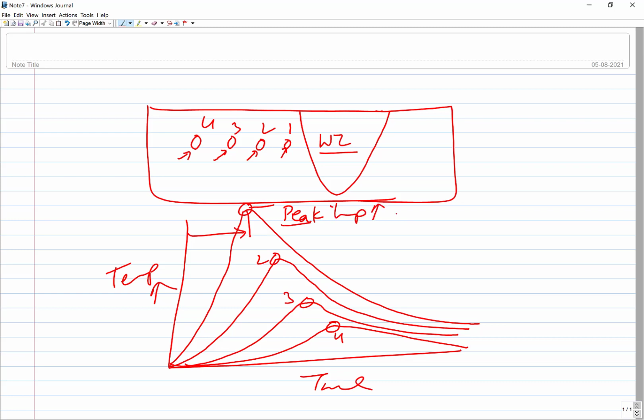Okay, and high temperature retention is also for a longer period. You take any particular temperature, you will find that high temperature retention is longer. So these are three things, and that is what is seen in terms of the heating rate, then soaking time and the cooling rate. These are three things which are seen with the help of these curves. So the point which is very close to the weld nugget area will be experiencing higher peak temperature for longer time, and the cooling rate is also high.